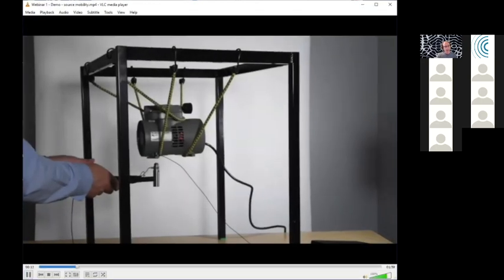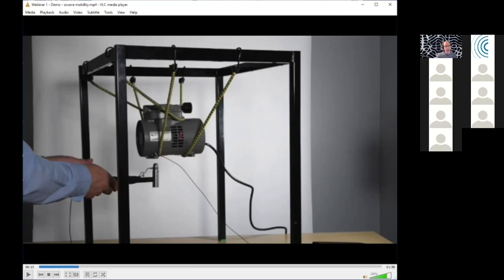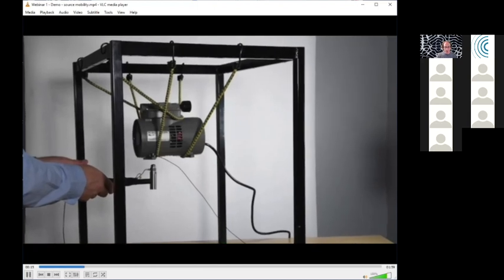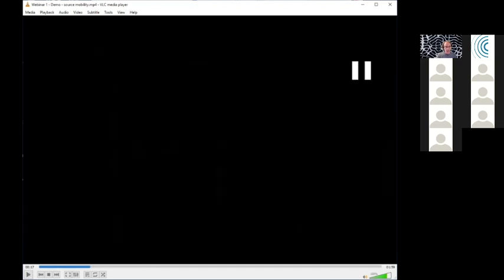So following on from Gary's measurement there, just again, we've got the force hammer, and at a fixing point here, we've got an accelerometer. So Gary's hitting it from below. And as before, of course, we average several times.